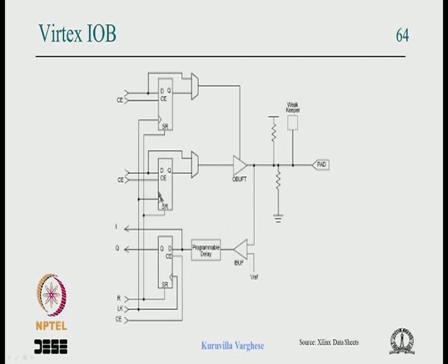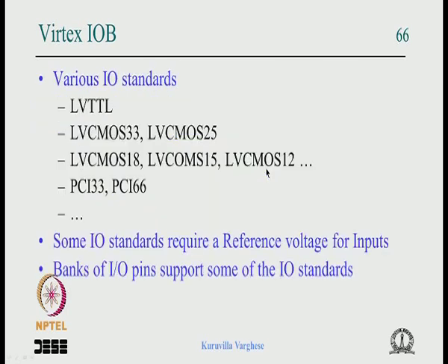So many times it's a wise idea to register the output before it leaves the pin, because that goes with the minimum delay. After the clock edge there is a TCQ delay, so there will be less timing problem for the input. Whichever circuit is using this output as an input will have less problem. Similarly, we have the input which, if it is asynchronous, we can synchronize. If everything is synchronized, this tri-state enable also can be synchronized, and it supports various IO standards, CMOS 3.3,